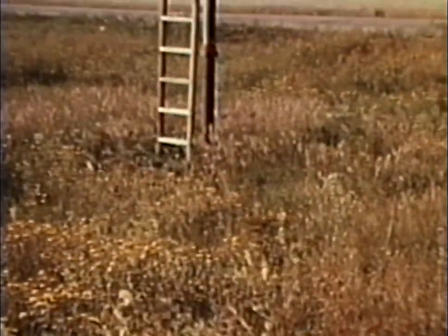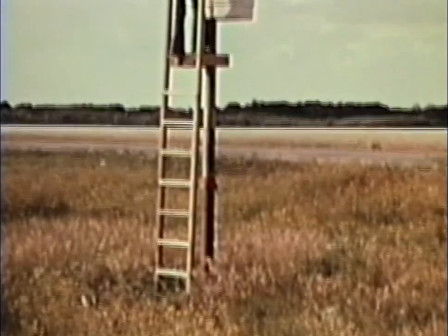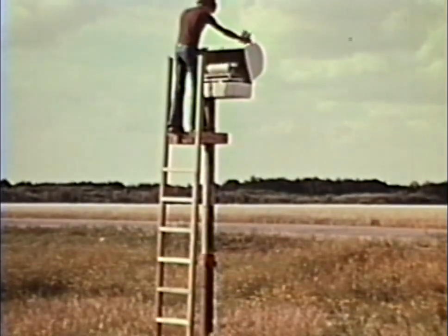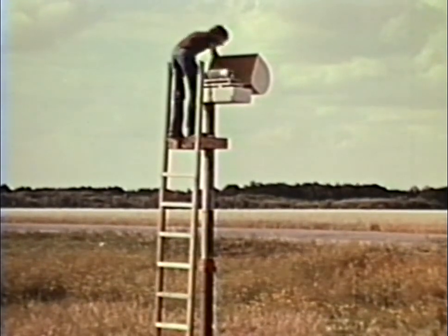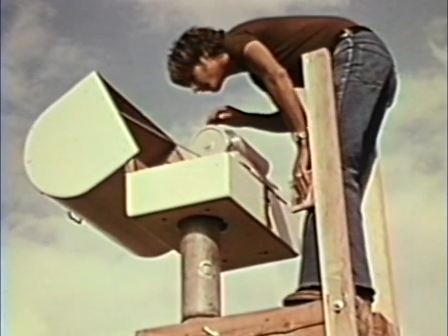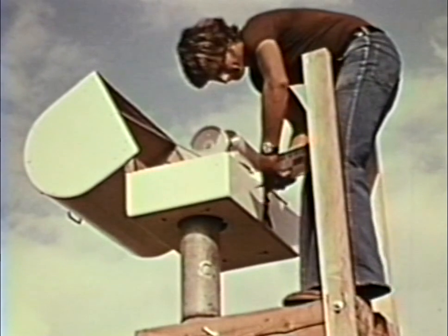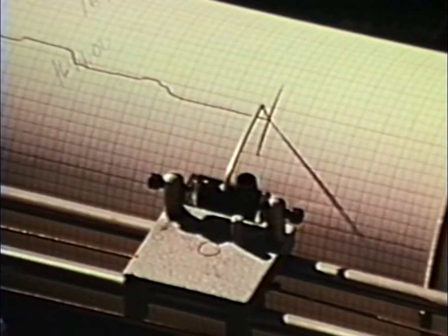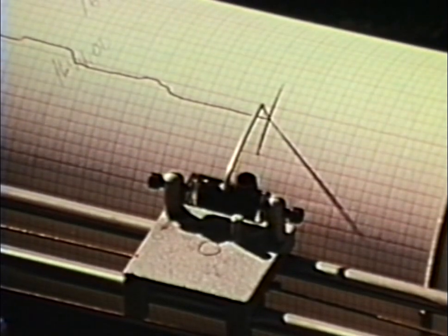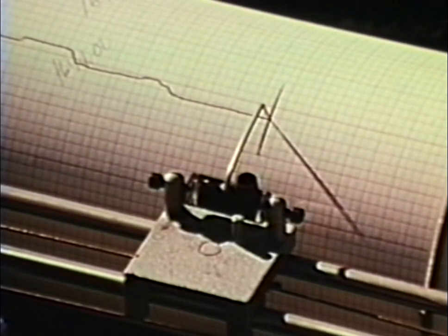The deepest well at this site is a flowing artesian well, which means that its water level is above the ground surface. Flowing artesian wells occur in many regions, another indication of the dynamic nature of groundwater systems. The casing of this artesian well was extended far above the ground for installation of an automatic water level recorder. The recorder monitors the changes in level of a floating device on the water surface. Observation wells with water level recorders now exist at thousands of locations throughout North America.